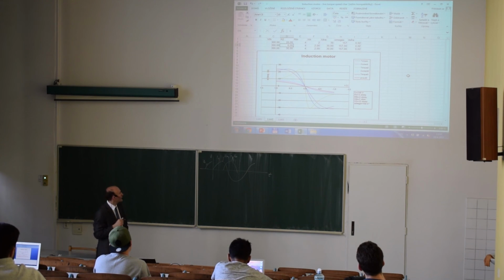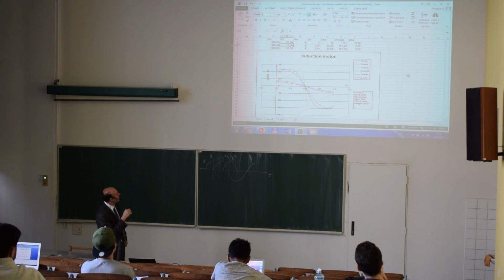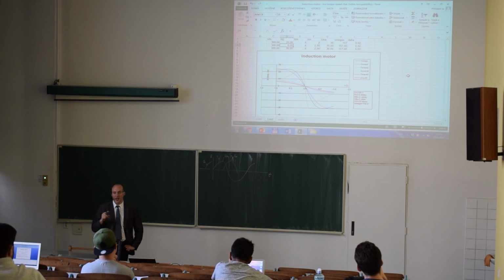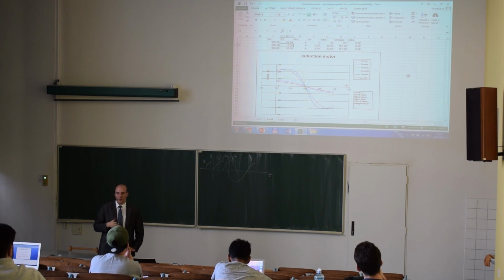But there is a difference in some other position. Somewhere here, at this part, we have slip 0. Slip 1 means it's standing still. So here, this value is startup torque. It means how much torque will be produced when the motor is standing still.